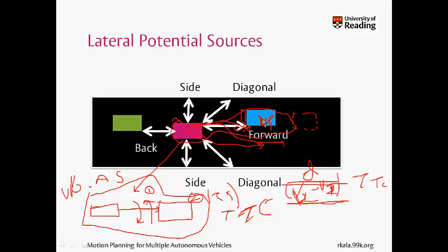And of course, if this vehicle is moving faster than this vehicle, my time to collision will be infinity. Basically, the two will never collide. So I need not turn anything. I need not even consider anything. I can simply go forward. So this was the first case for the forward direction. I've taken time to collision as my magnitude of steering. If time to collision is very small, my steering would be very high. If time to collision is very high, my steering would be very small.